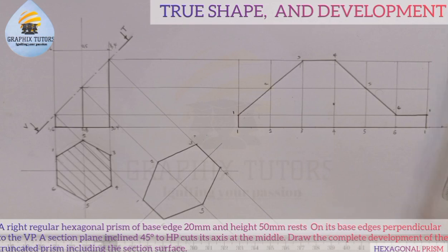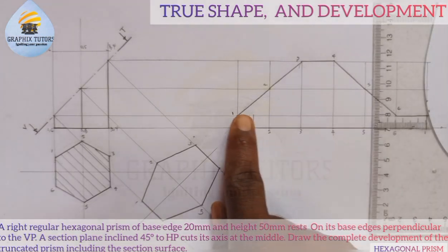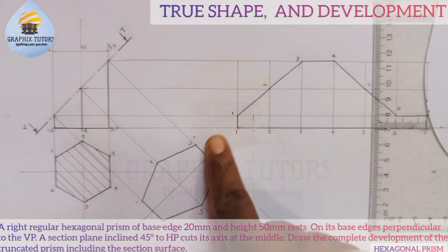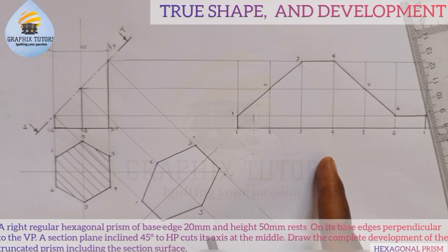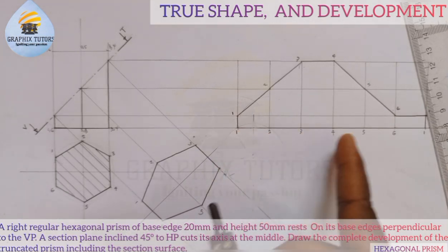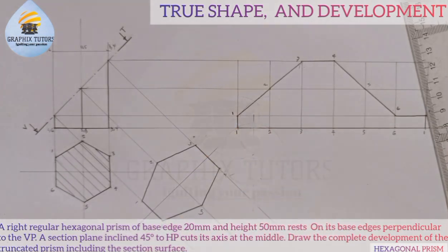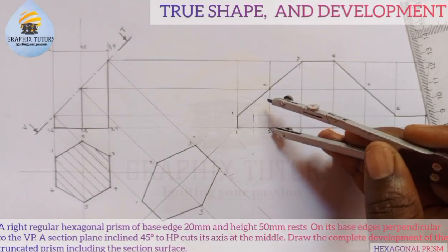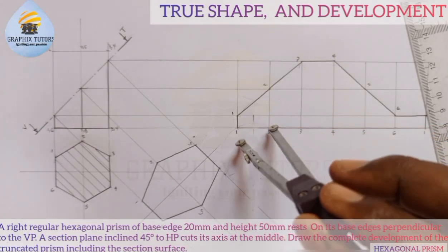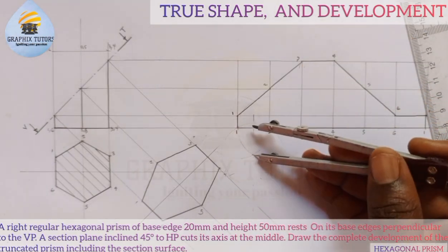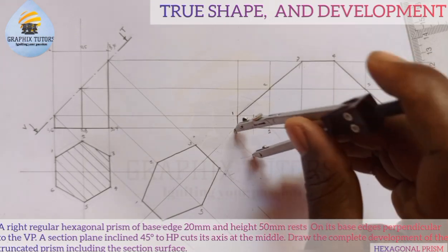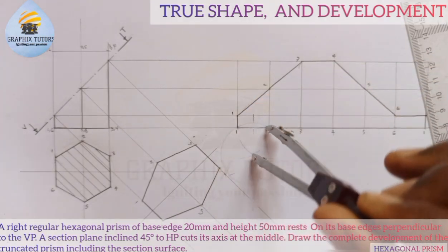You can see that. Now the next thing you do is to draw the surface here, what we call the bottom surface, right? That is the bottom surface. It can be anywhere. It can be between 1 and 2, 2 and 3, 3 and 4. But I will put mine in 1 and 2. So in doing that, I'll just place my compass here, these two radius here. I'll strike an arc this way, right? So where they meet in this manner, I will draw a circle this way.